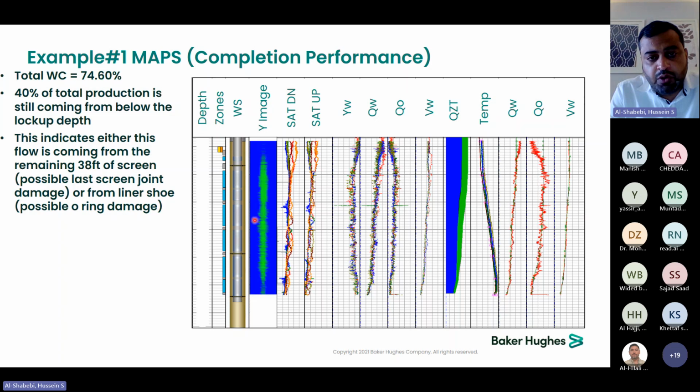This is the image of the holdup. As you can see, the middle is the top side of the wellbore, and the bottom side is the edge of this image. This is the spinners' distribution for the down and up pass. This is the holdup measurements from these sensors, converting the array or the image to one holdup measurement. This is the rate calculation, QW and QO. And this is the mixture water velocity. And this is the constructed profile.